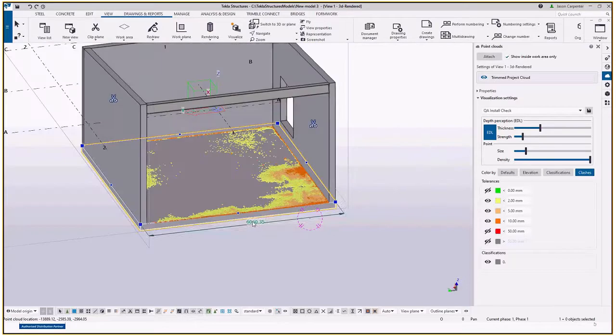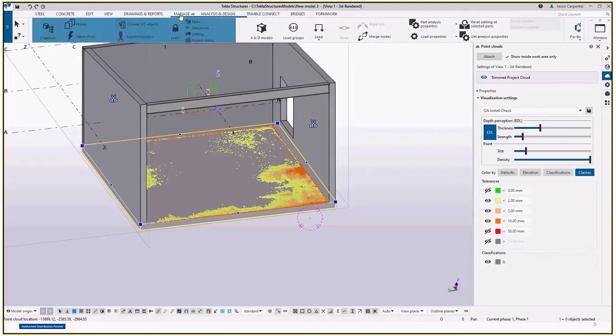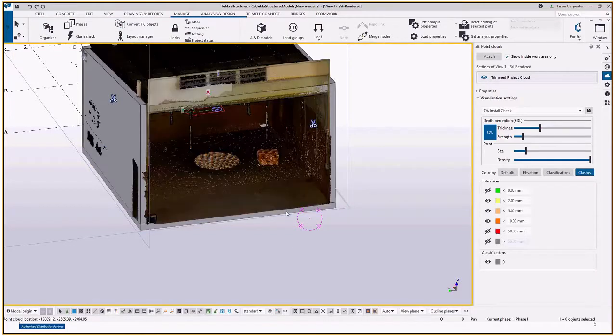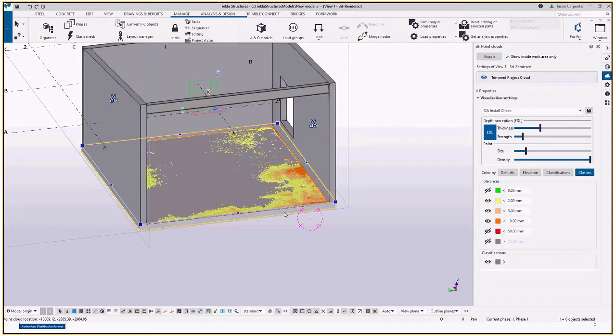So obviously a scan is well and good. Now you can possibly do this in the X7 at the moment with the overlaying of the data. But at the same time, you can bring in your own layout manager and start creating some example points around these, by snapping onto the point cloud, and you're able to identify these locations using the point manager, export to your total station, and start setting out where these high points are. Cool.